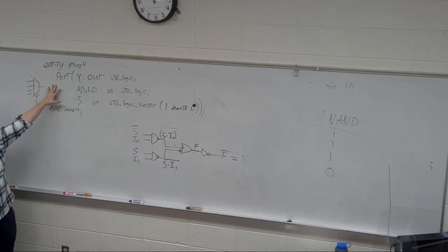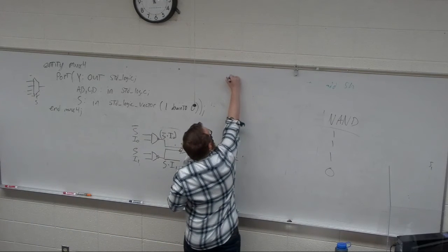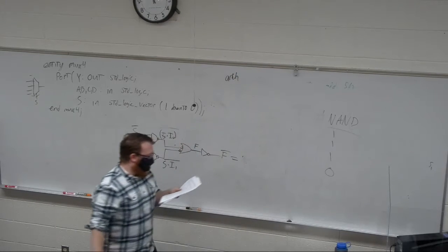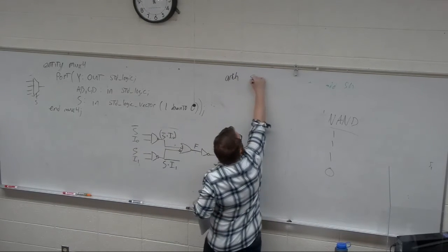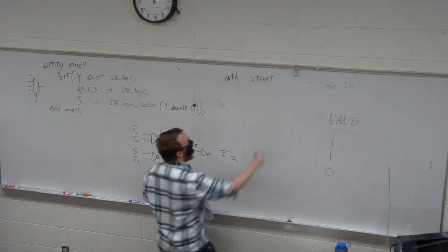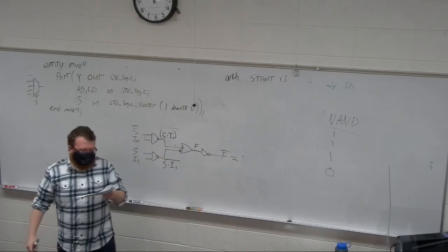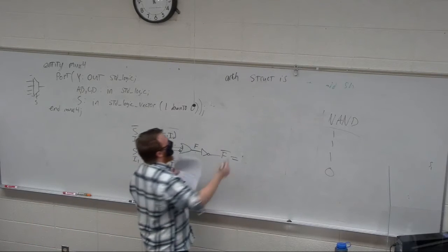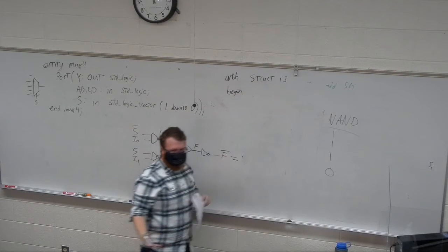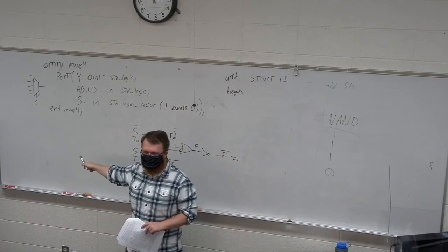Ports that see the outside world. And then we move on to architecture. I'm not going to write the whole thing out. Architecture, and you name it something like structural is, right? And then in there, we can just tell it the structure of what a mux is doing.